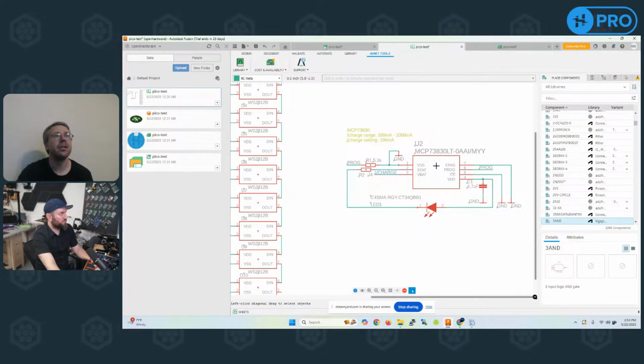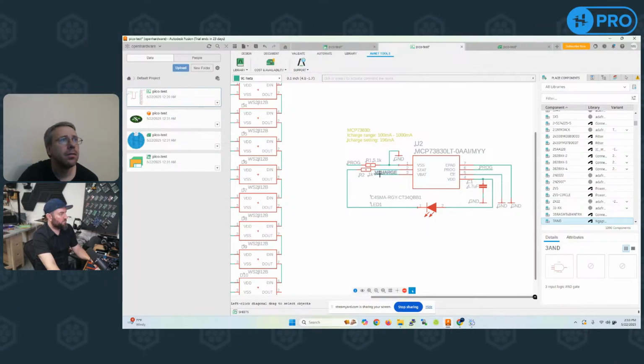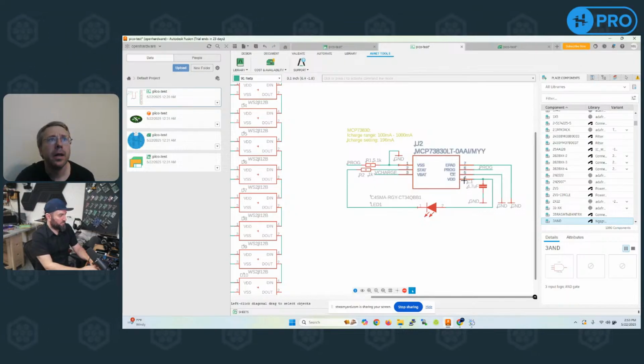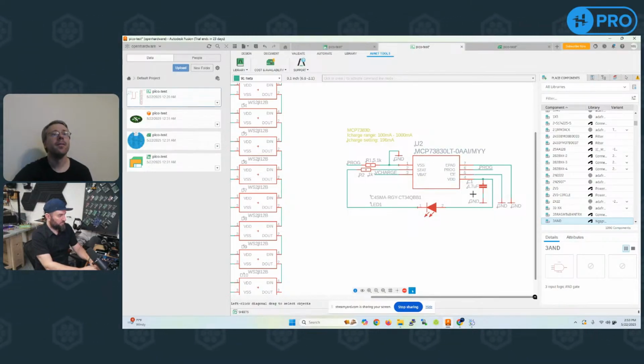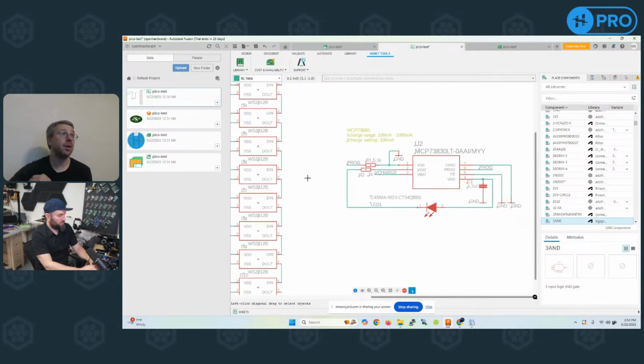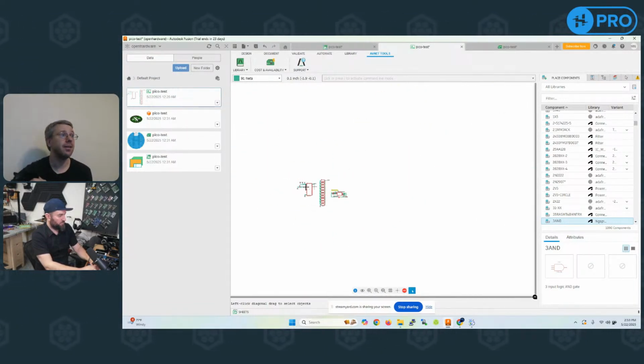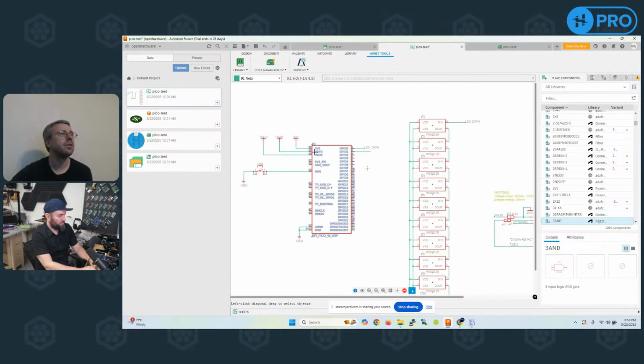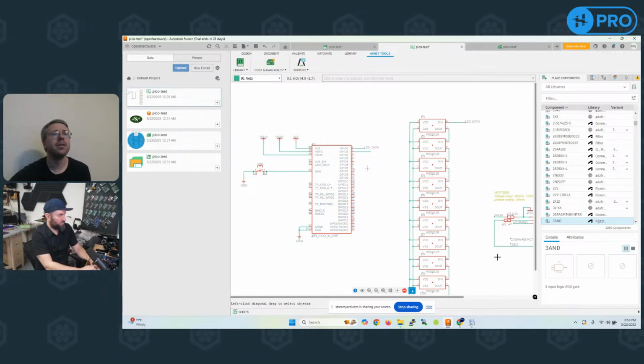We got a battery charger circuit, V-charge, which would connect to your battery terminal, and VDD. I'd have to look at the data sheet for it. I would find out if it's possible to connect it to this guy, which I'm assuming I can probably do using the VSys or VBus.